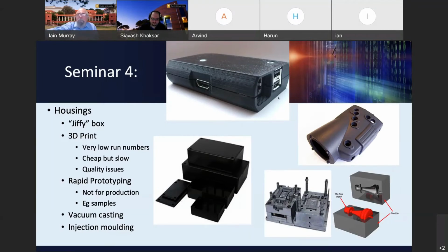But being 3D printed, you've got a couple of problems. The first one being you get a fairly rough surface, so it is not something you'd want to be selling to people where they're going to be handling it all the time. Probably the biggest drawback of them is structural strength. Because it is layers and layers of plastic, which we can see here, they don't have any strength in the direction of the layers. So if you print something like a ruler, and you print it with the layers going vertically in this case, it'd be very easy to snap it if you bend this way, because there isn't a great deal of strength between those joints. So you've got to be careful which way you print it, but they still don't have a great deal of strength.